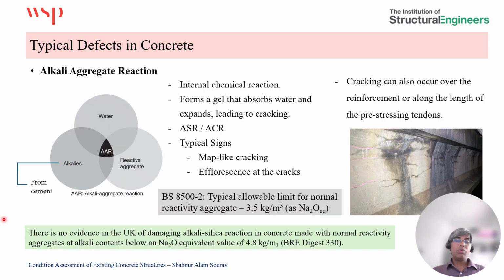Now on to the chemical reaction process of the concrete. Alkali aggregate reaction is an internal chemical reaction where a reactive aggregate reacts with the alkalis in the presence of water to form gel-like substances within the aggregate particle. These alkalis usually come from the cement, and when the gel is formed, it can absorb more water and expand, which can lead to cracking. There are two types of reaction.